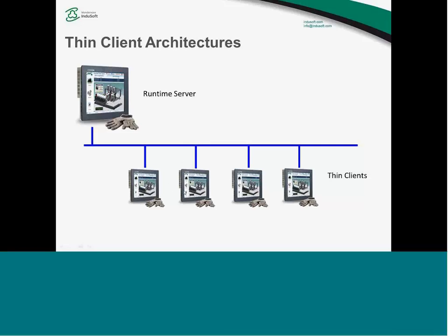Secure Viewer, on the other hand, might be for a large process or a large machine where maybe you want a duplicate display at the other end of the machine. Secure Viewer really looks just like the real runtime application. In fact, sometimes you can't even tell the difference. That's the difference between the two: one would be in an office environment, where you just point the browser to it, and the other might look like another duplicate HMI. You get one of each with the runtime license, and you can expand that up to 128.